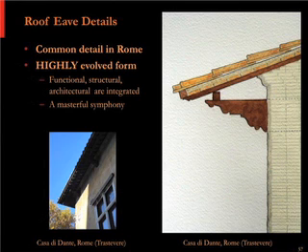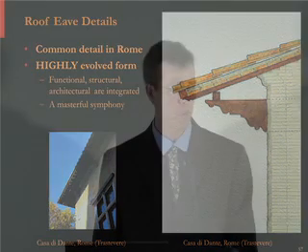You could draw a 30-degree line on that, and if you had even 30-degree rain, wind-driven rain, which is very, very extreme, that wood would not get wet. So they kind of did everything right. So if it does get wet, it's going to survive. And then they have this great roof overhang to really protect it and make sure it doesn't get wet.